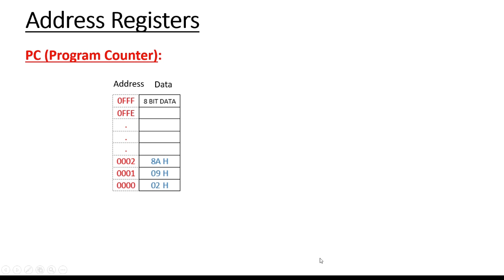The program ROM may be on chip at addresses 0000H to 0FFFFH, and external to the chip for addresses which exceed 0FFFFH. So the program counter is used to access the internal ROM as well as the external ROM, which has a total address range from 0000 to FFFF.